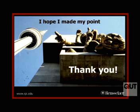Question, just with the flow that you're putting around the building or outside of the building, is that something that's just constant, or was that being varied? The study you have there is constant flow, but we're about to go to the wind tunnel when I go back on Saturday. Next week we'll be in the wind tunnel looking at pulse flow, because what we're trying to do is put in as little energy as required to get a maximum response. So we're actually going to use resonance in our favour this time. We're going to be pulsing the flow at such a frequency that it causes resonance of the separating flow, and so it reattaches. So that's the problem with the airflow here.